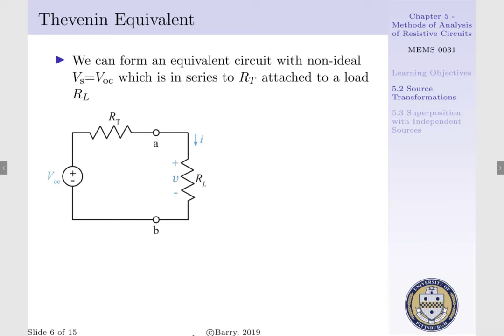Now say from example 1 that although we did not know the source driving a voltage potential and current through a resistor, by connecting an open circuit voltage source, V sub OC, in series with the Thevenin resistance, R sub T, we could connect the source to our resistor R from our previous example and determine our voltage potential across and our current running through it.